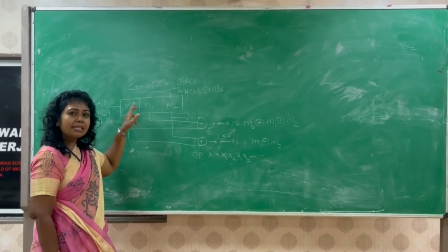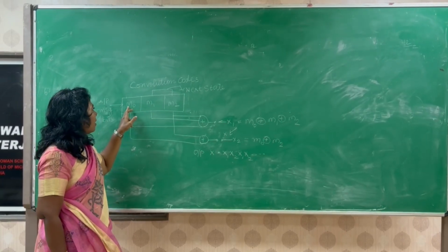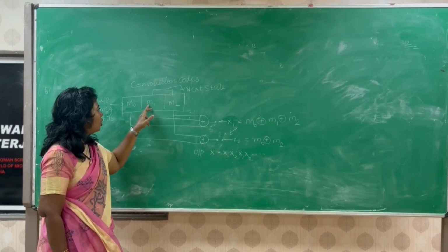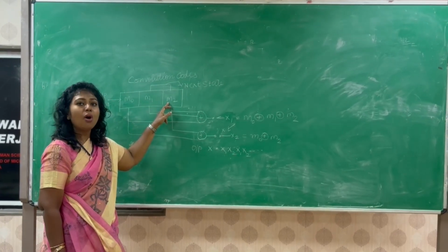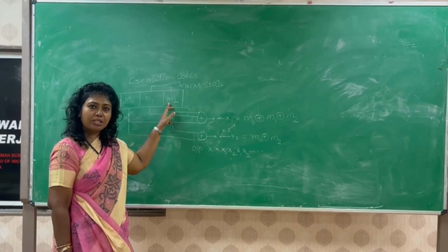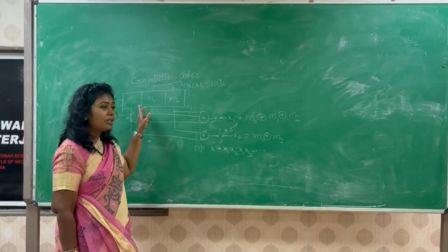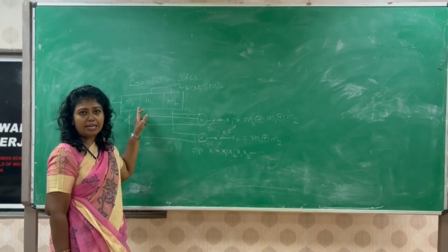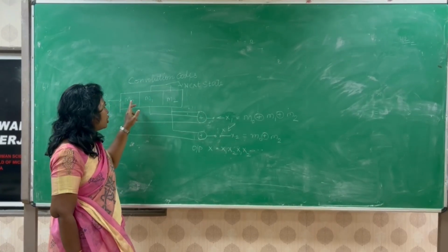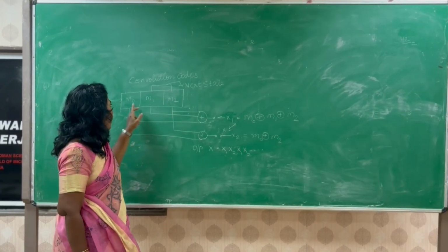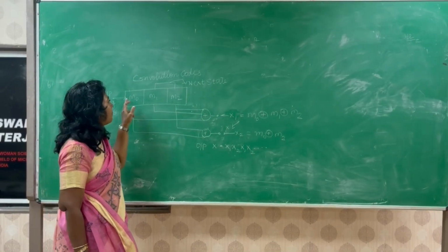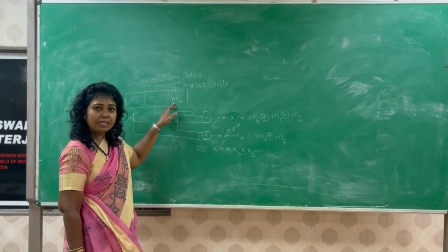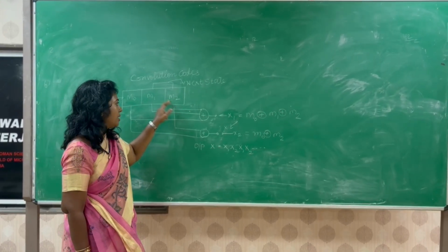Then, in the next clock pulse, the content of M0 is shifted to M1. The content of M1 register is moved to M2. Whatever was present in M2 register will be discarded. So this is how the data is moved from one shift register to the other. M0 is the register which takes in the input bits. M1 and M2 represent the next state of the registers.